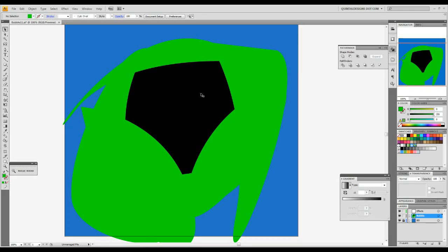We're going to select the black circle that's underneath. That's the edge we want. We're going to hold down Alt on our keyboards and tap the right arrow once while you're holding Alt. Then let go of the Alt button on your keyboard. You'll see your cursor change back. And tap left once on your keyboard. Now what we just did is we made an exact circle. We copied it 1 space to the right and then moved that copy 1 space back to the left, effectively making an identical copy of the circle.